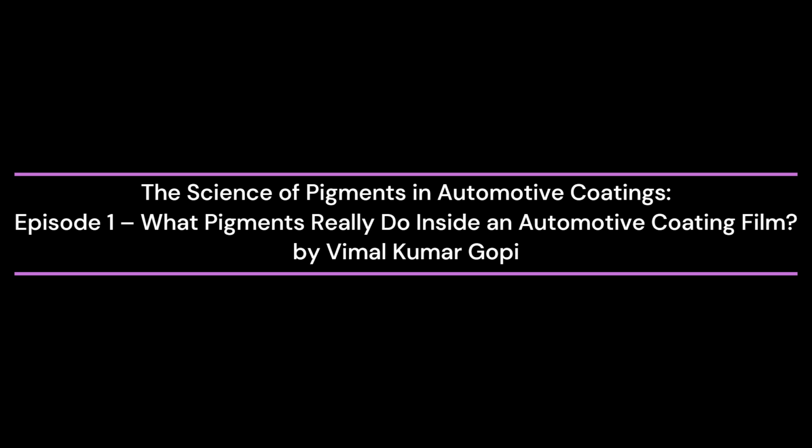Pigments also influence application behavior. They affect viscosity, flow, leveling, sag resistance, and spray atomization. In the case of effect pigments such as metallic flakes, orientation during application becomes critical, as it directly determines visual properties like brightness, flop, and color travel.